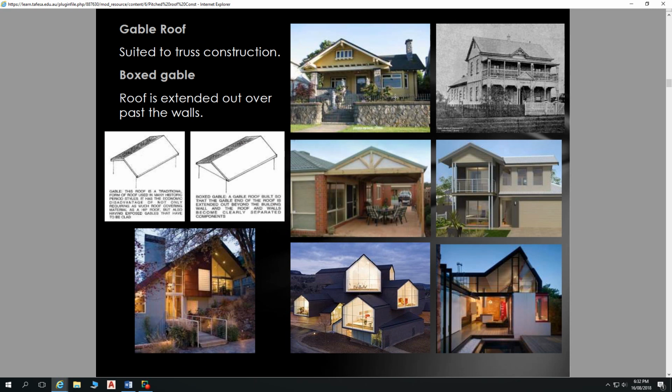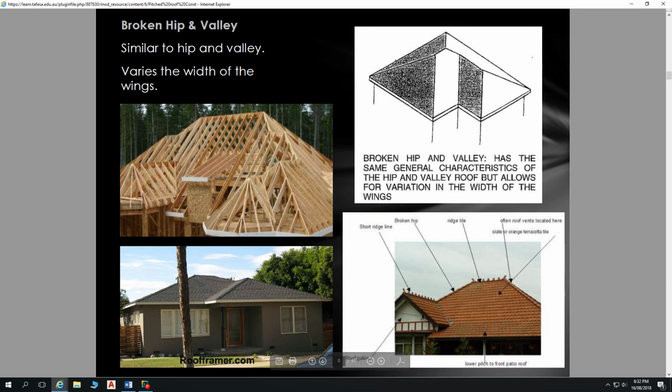So that's with our hips, and then there are all sorts of permutations of that. You can look at some complex floor plans, and then have a whole series of major hips, minor hips, major ridges, minor ridges. So this is our major ridge up here. This is our minor ridge. This is our major hip here, our minor hip here, and this one that starts and then terminates at this minor ridge is called a broken hip. So that hip is broken up by this minor ridge.